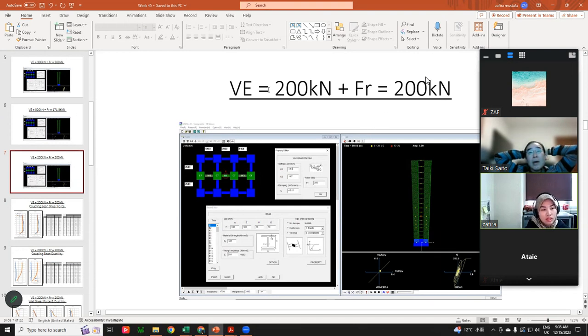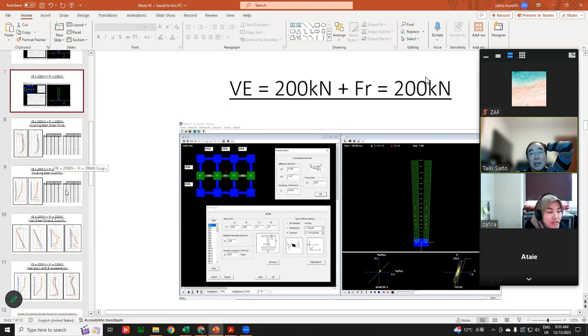Well, I think you should first analyze only viscoelastic. Only viscoelastic? Yeah. Then you can find how much shear force is in the beam. Then you want to reduce, I mean, you want to limit the shear force to less than the maximum shear force of the viscoelastic damper. Maybe we can also do the lambda parameters, say 1, and then 0.8, 0.6, and 0. Okay, I can try that.